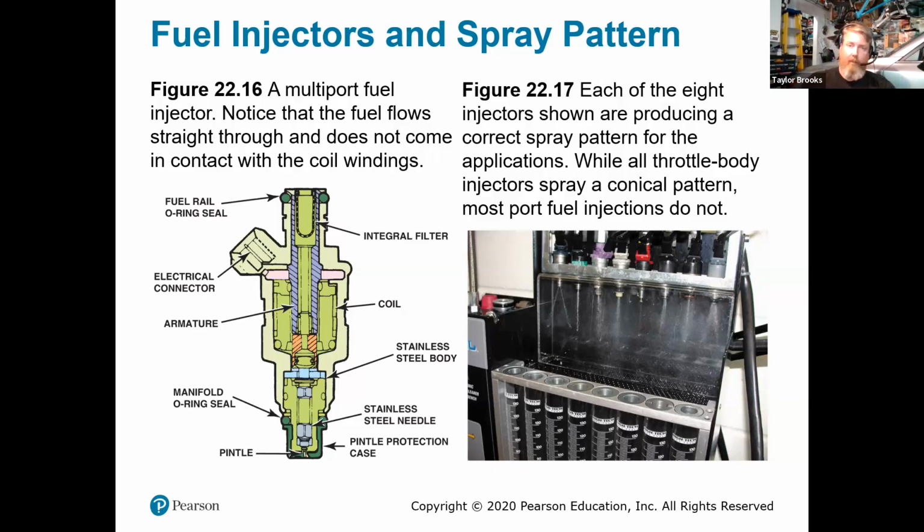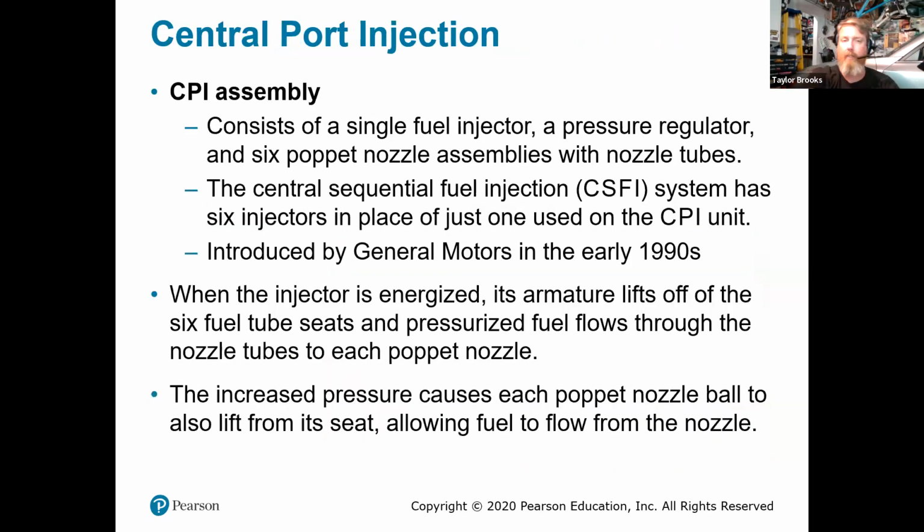I found that it's extremely helpful because it allows you to know that all the injectors are consistent. And we would do this with the time attack cars as well. With the cars that we were running pretty high horsepower on, that we needed consistency with, we would buy a grouping of injectors and have them all match balanced, so that we would have a set of injectors that were going to work in a particular engine.